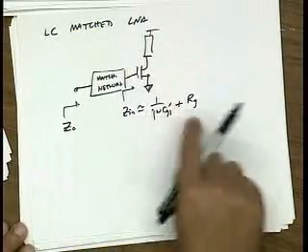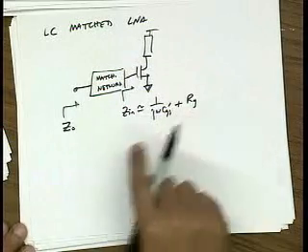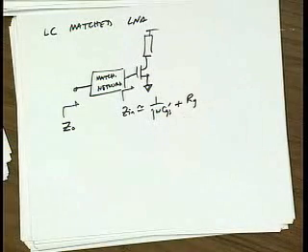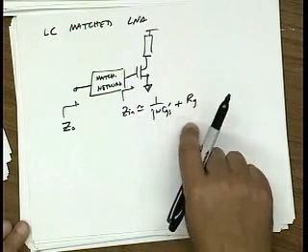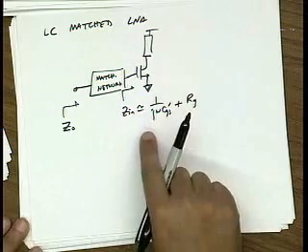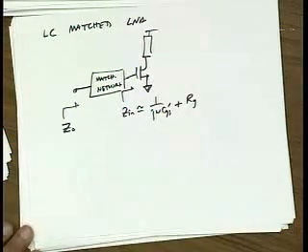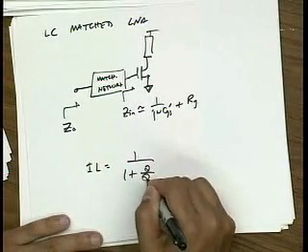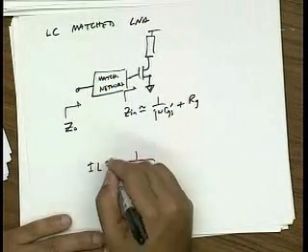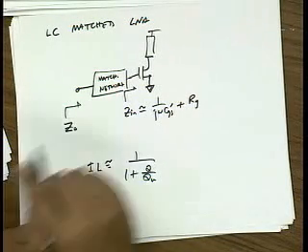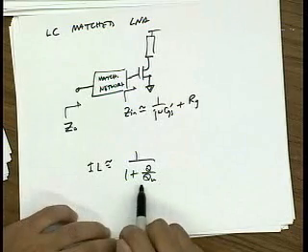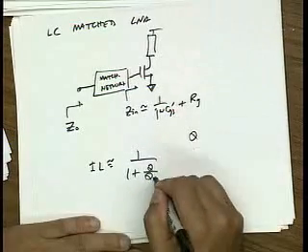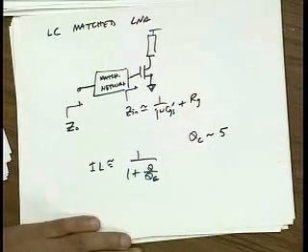So remember, the Q of your network is proportional to the square root of R high over R low minus 1. So if you have a 50, your Q is going to be roughly square root of 50, roughly 7. And remember, the insertion loss of a matching network is roughly 1 plus Q over the unloaded Q of your component. And it turns out that if you're building this thing on chip, it's pretty hard to get component Qs better than, let's say, 5.